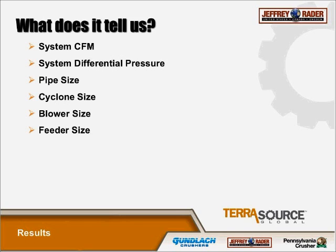If anything changes, the system likely will not operate correctly. If the system's designed too small, obviously it won't convey the material properly or at all, and have material just sort of slugging down the pipe as pressure builds up behind it, then shoot forward a little bit more and pressure builds up, and not efficient at all, increased wear. And then a system designed too large is also a problem, because you don't want to waste power and could have too high a velocity and the air just runs over the material. So in either case, it's very important to define a set of specifications and stick to them.